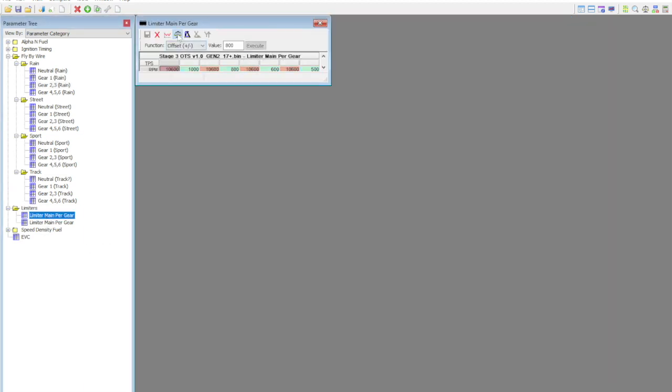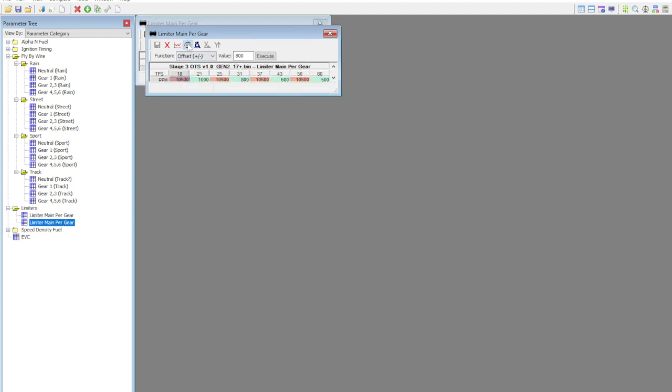I don't think I changed them, do I? No, I don't change it at all for our stage 3 tune. Now, a lot of tuners can raise rev limiters on the 1290 engine. I know people I trust who raised them as much as 500 to 1,000 RPM without grenading anything or breaking rods or spitting out pistons.